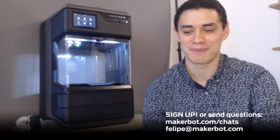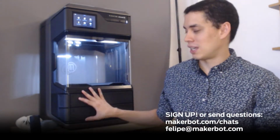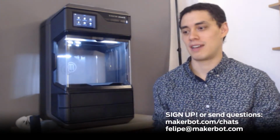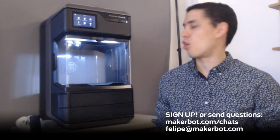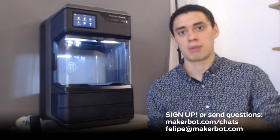It was a really fun webinar yesterday, just about how you actually get the method to print carbon fiber, what the best practices are, what issues I've encountered, and an overview of the support materials that you can use. You can use breakaway or PVA or SR30. What are the pros and cons of each of them, right? So if you have any more carbon fiber related questions, do let me know in the comment section.